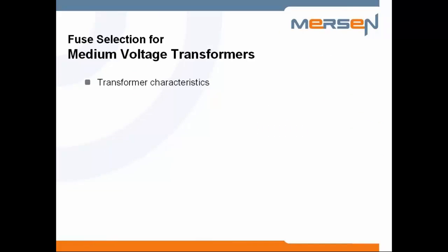Fuse selection for medium voltage transformers has to be looked at because it really is a limiting factor. Two of the main things that you have to look at when selecting a fuse for a transformer is the full load current. The fuse must carry it without overheating and opening, but it also must pass the inrush currents for the transformer when you first energize.